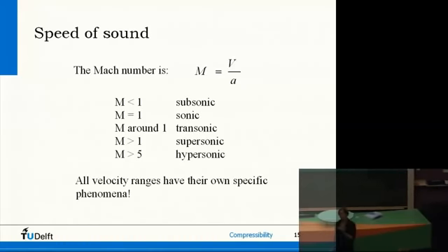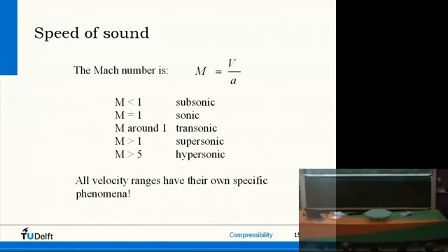But of course we have also high speed subsonic, so subsonic flows above 100 meters per second. And this 100 meters per second is approximately Mach 0.3. So low speed subsonic, incompressible flow assumption, is about when Mach is below 0.3. But when Mach is between 0.3 and 1, you do have relevant density changes already, but the flow speed is, of course, still below the speed of sound, subsonic. Then Mach is 1, they're exactly equal. Sonic, what you have inside the throat of a supersonic nozzle, a wind tunnel, or also can be a rocket engine.